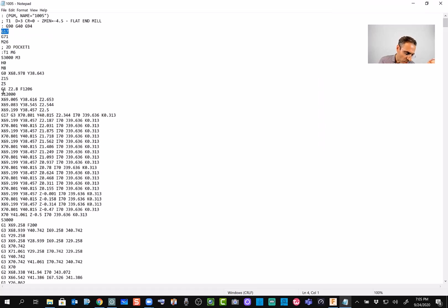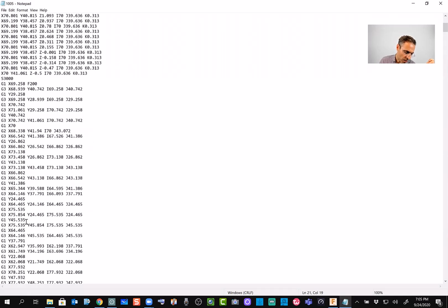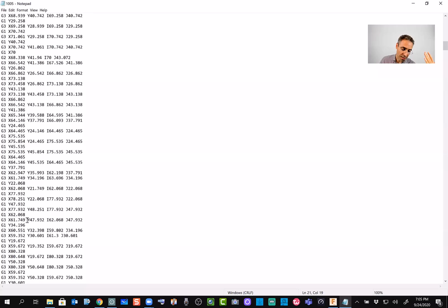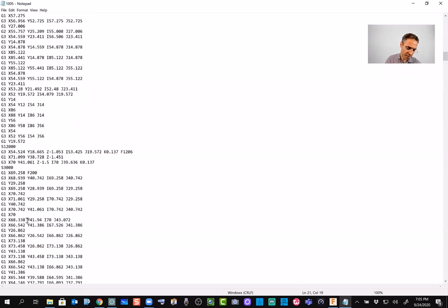And at some point, it is just X, Y, Z. It's just the coordinates. You say, my first point is this X, this Y, this Z, right? And this is the I, J, K, which is like the orientation of the tool. And then another X, Y, Z, and so on. All these things, the program has created for us.